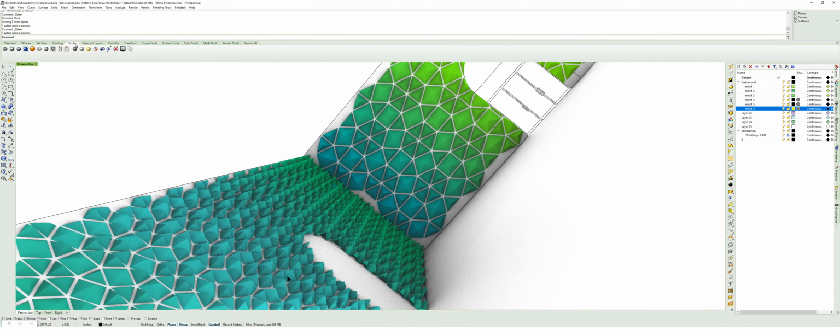So I'm going to use a 3-point surface here. And actually, before I do that, I'm going to set my C-plane to vertical. And then I'm going to draw that 3-point rectangle and just let that be my feature wall. Give yourself some context wherever you want. We're just going to go ahead and do a straight wall in this instance.